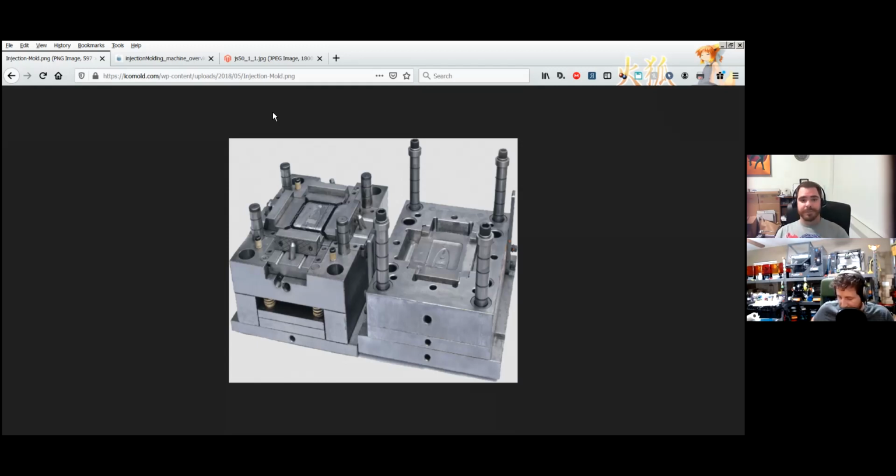But if you're looking, let's say if your order schedule's 100 a month, that's no problem, generally speaking, for 3D printing. We have a client right now that orders between 50 and 100 pieces a month. He has a just-in-time inventory system, so he keeps 12 or so sets in stock. When he reaches 6, he goes ahead and reorders another 12.